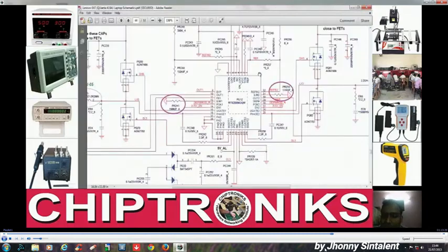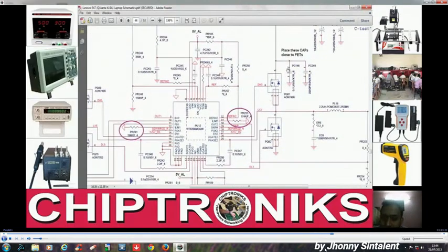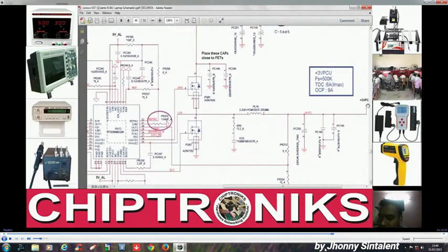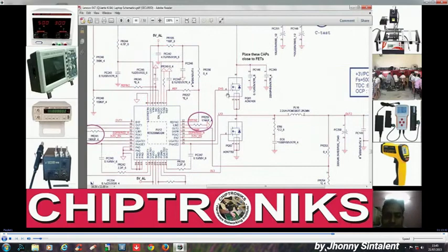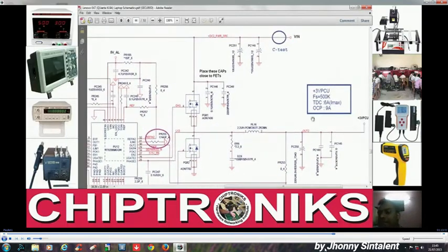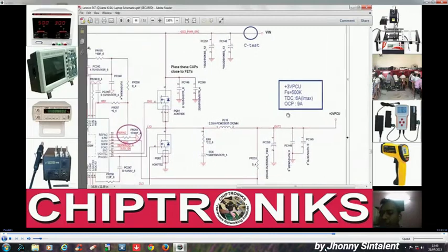If we see in the schematic, it might damage these MOSFETs, because at time t equal to 0 this voltage is 0, so this will give a feedback over here, and this will generate very high pulses, this high drive DH3 and DL3, and that might damage these MOSFETs and the components which are connected to the 3V CPU power line.